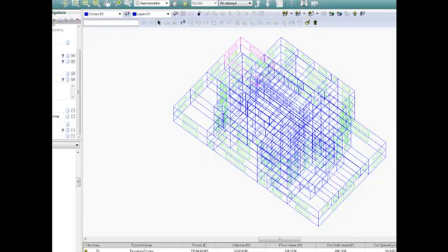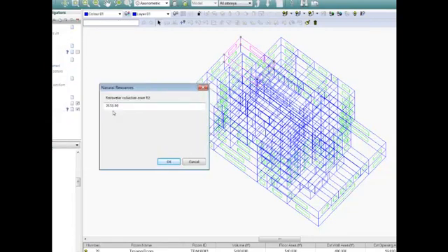Okay, so the first one I'm going to pull up is going to be natural resources. And what natural resources is going to do, and I'm just going to pull this up, it's going to give me the ability to see if I had an analysis to run based on the inputs that I have set inside of Affinity, meaning that this is an office building. And when I assign office, there are other things that are assigned, like there are this many people per square foot. My occupancy is taken into account there. It takes into account the hours of operation. It's going to take into account the heating and cooling set points.